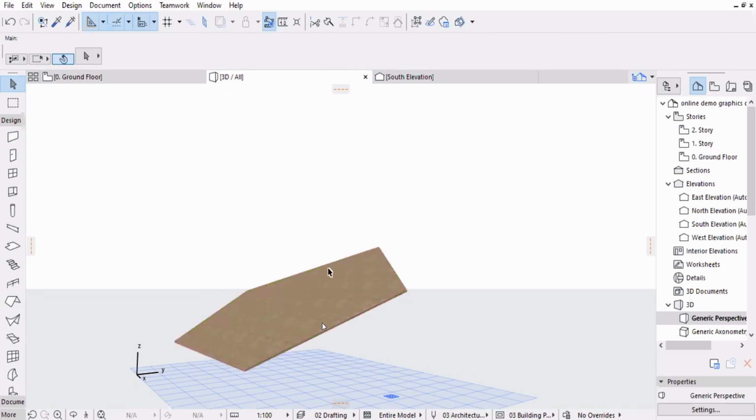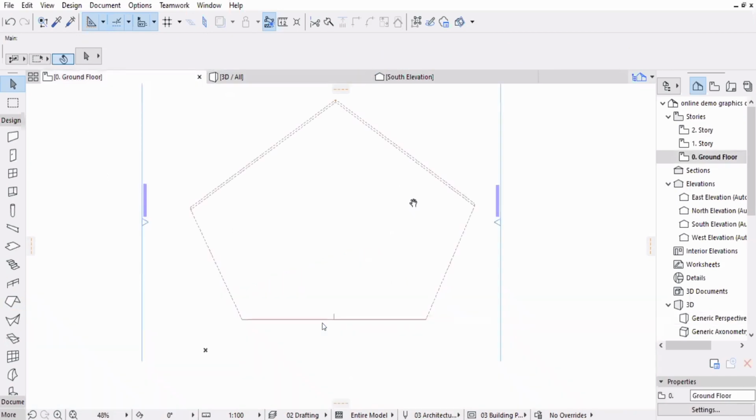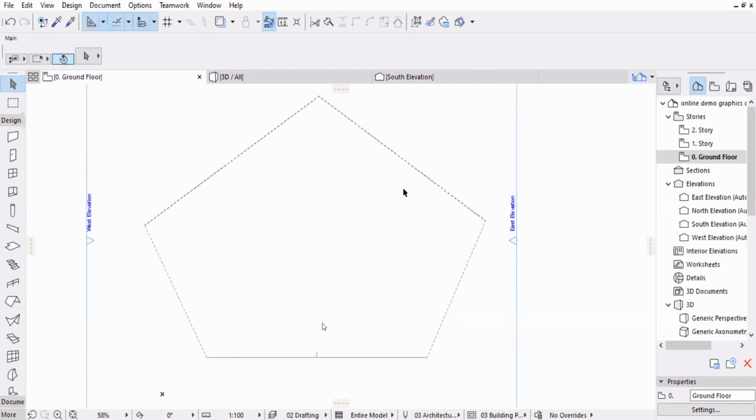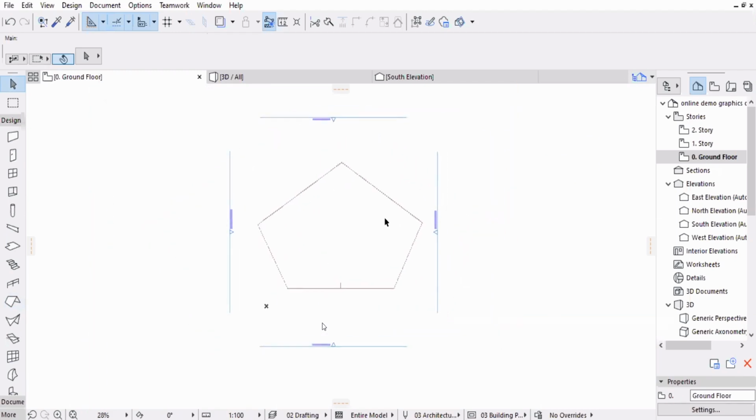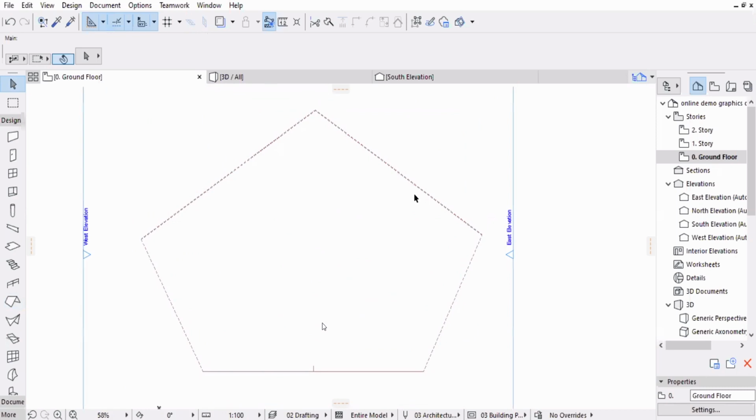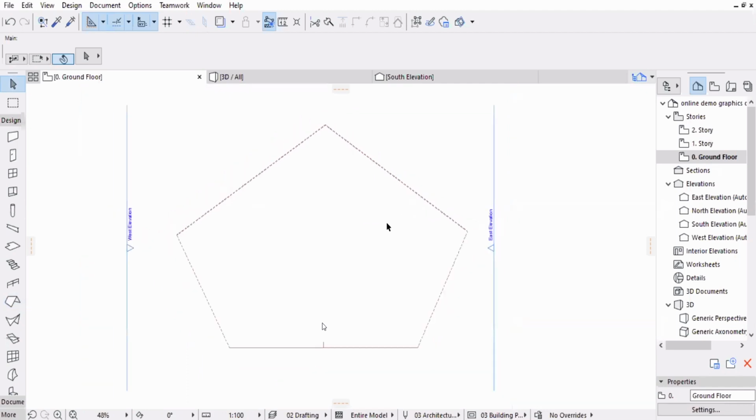Right, so we have drawn a roof, and guess what? If you want to draw a wall out of a roof, you can use a magic wand and draw a wall out of a roof also. It doesn't have to be always the other way around, that you have the walls first and draw the roofs. I will also show you how to draw roofs quickly when you have a wall profile. You have particular boundaries of walls, and you want to draw the roof in the same shape as the wall enclosure, with equal slopes and everything. I'm going to show you that next.